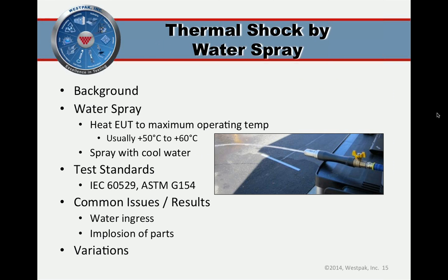So the scenario to envision here is if you have a product outdoors in a very warm environment, so we'll take the desert, and you have radiant heat energy from the sun, you can see heating of 20, 30, or 35 degrees C above the ambient air temperature. So a very warm day might be 40 or 45 degrees C. We're talking 110 F. And you may have a 30 degrees C temperature rise above that. So you could have a product surface temperature of 70 degrees C or warmer. And there are tests, as an aside, to define all that.